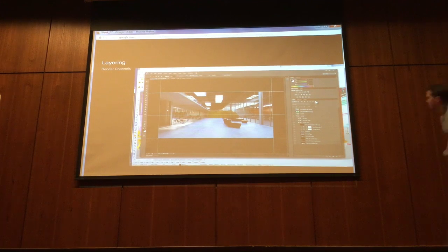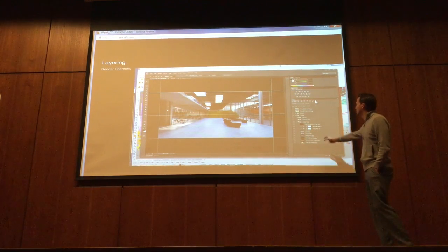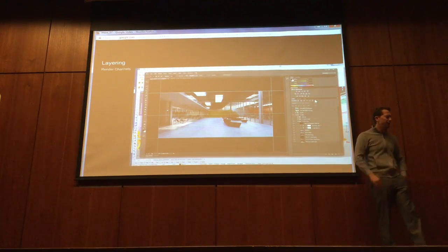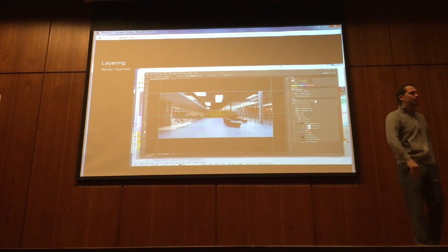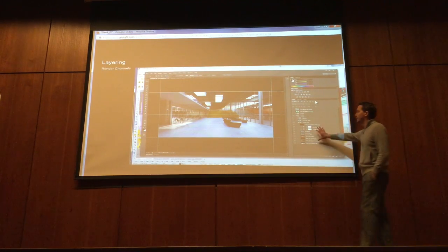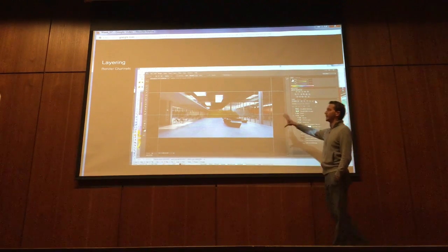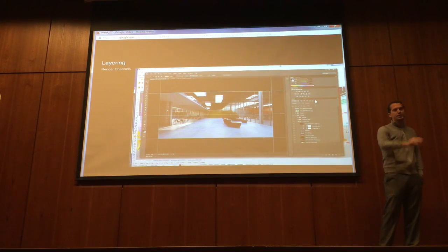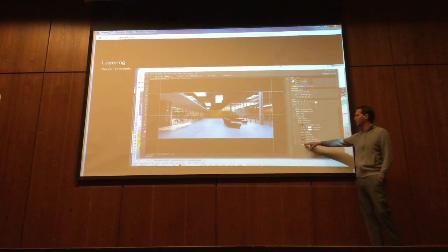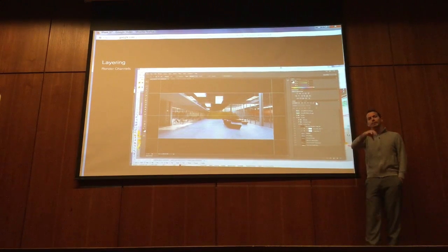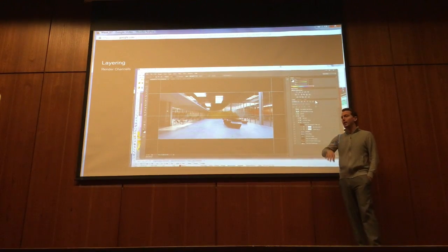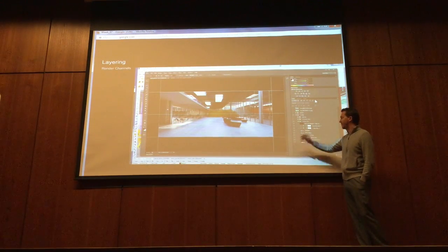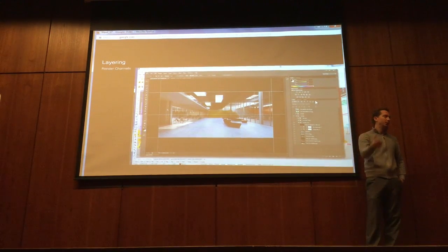So note on this, guys, one thing I want to point out that's not clear on here. Chris May, I'm going to guess that he used V-Ray on this one, but maybe he used something like Maxwell, and maybe he doesn't even know what the materials are. We're just checking lighting. The first thing I do when I set up any render is I also set up a Photoshop file, and I'll do something called place. Instead of opening my render file, I will open that file, and then I will immediately place that same file in the file and delete the original layer that I opened.